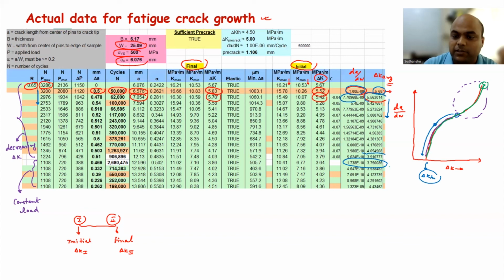And that is what is shown here. So your delta K, if you see, is increasing here, and on the top, from this point up to this, your delta K was decreasing, right? So your delta K is increasing, and you can see at the bottom your crack growth rate is also increasing, right? So you are going to follow the same path, and finally you can obtain the rest of the part which was not obtained before.